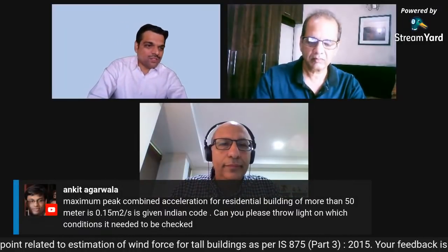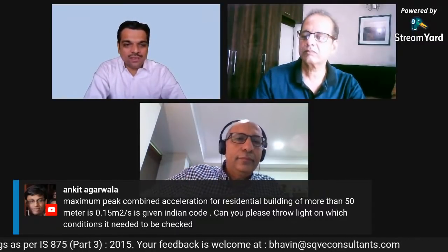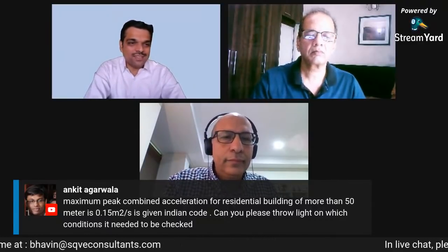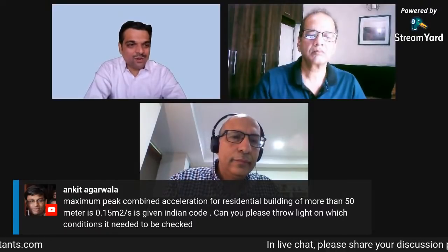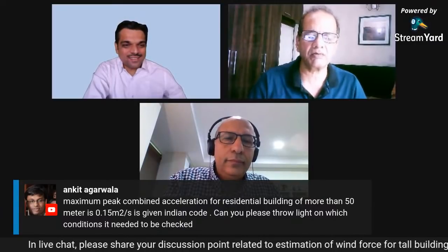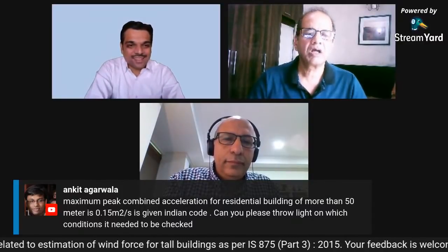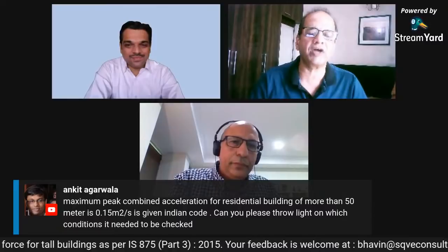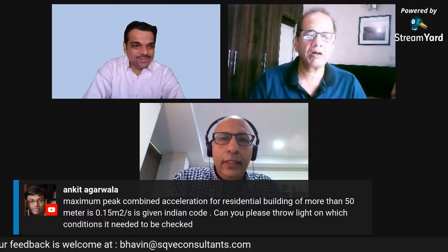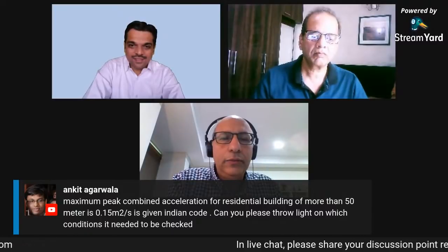Okay, one interesting question from Ankit. The maximum peak combined acceleration for a residential building of more than 50 meters is 0.50 meter per second square, which is defined in the Indian code. Can you please throw some light on which condition it is needed to be checked? It is written in the code also, on the 10 years return period serviceability condition. You have to check this acceleration, and 0.15 meter per second square is for residential, but that's a 10-year return, a 1 in 10-year event.